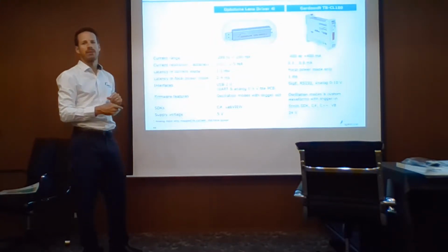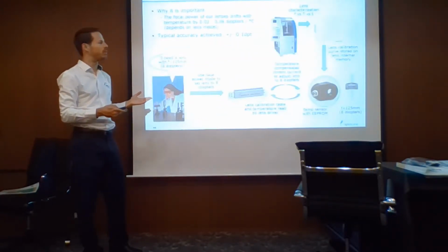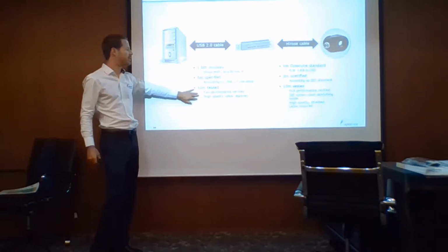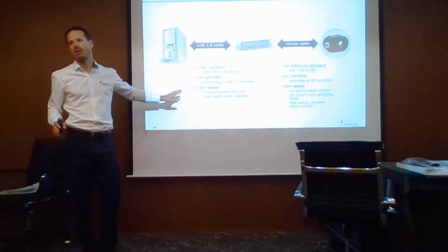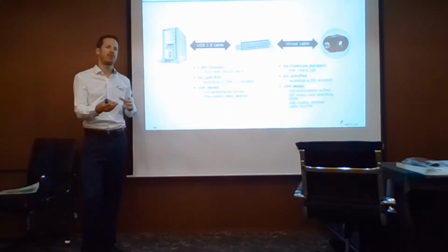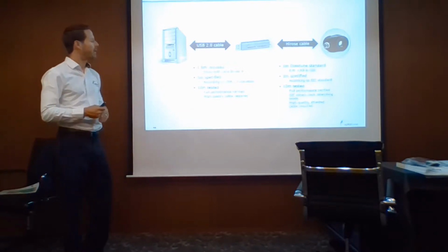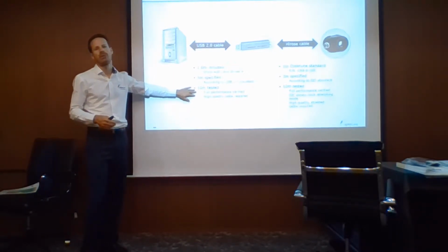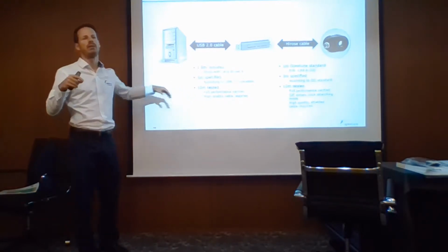That's why the USB cable has to be good quality and not too long. Now we've tested 10 meters. Basically it works, okay? But we don't give any guarantees for 10 meters, because maybe if there's some interference, in general you will have a bit less performance, less current output, because you waste a bit of the power over the cable.